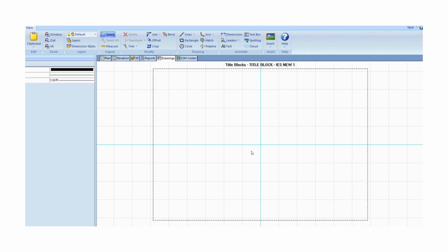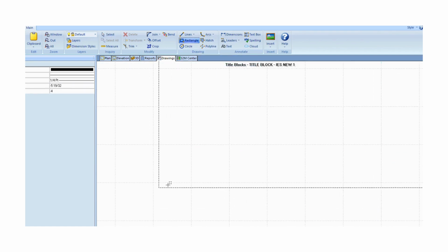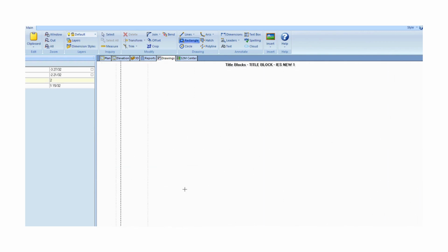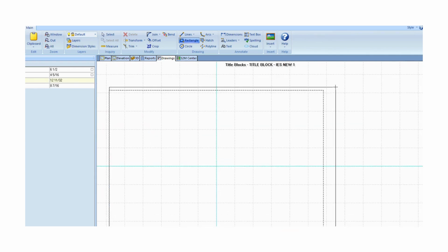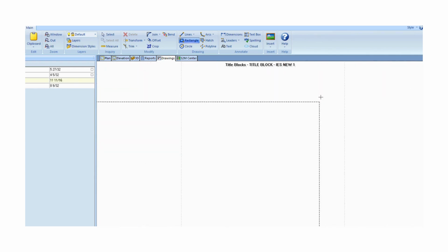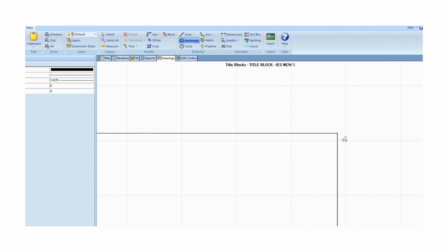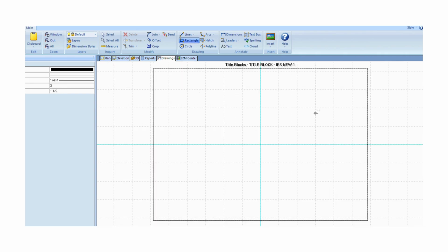If you create the title block in A3, whereas you need A4, then after creating it, if you select that on that particular page, the title block will not come properly. So let's begin. I'm just going to give a border. It is more of an AutoCAD drawing only, so we have to create it. We have used the line commands and the text commands in order to give out details.